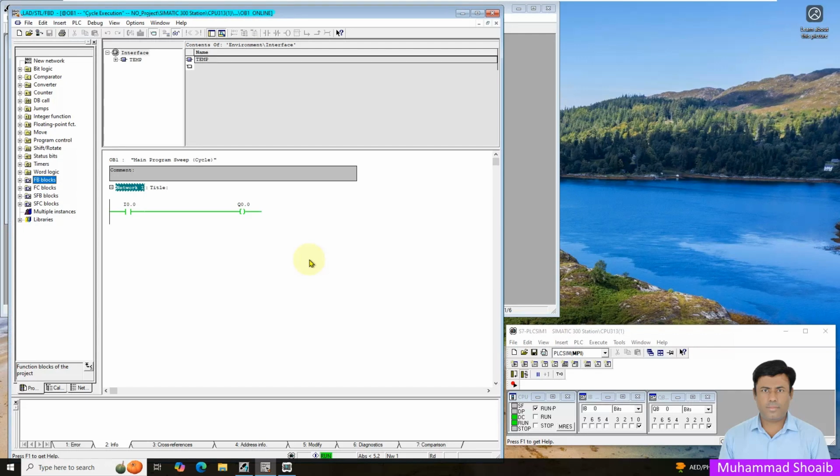Alhamdulillah, we learned in this tutorial video what a NO contact is, how we can program it in a PLC controller, and we also learned one practical example, like if we have a selector switch and we want to turn on the motor, how we can program it in SIMATIC Manager.